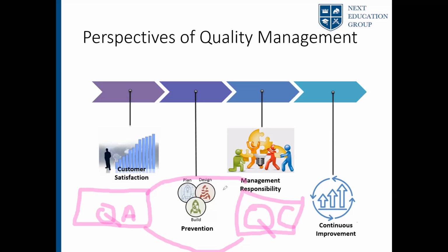So the whole idea is if you find a product which is not meeting the right standard, maybe like a customer complaint through a warranty claim, we would be able to trace where the tire was built, from whom we purchased the raw material, where the recipe was done, how long it was stored in a warehouse, which warehouse it was stored, how it was transported to the country of destination, all that. So we could look at the batch in which it was produced and then examine, are there any other defective products? Are there any other issues with the same batch? If so, we can recall the batch without revealing it to the customer, without customer complaining, more proactive measures.